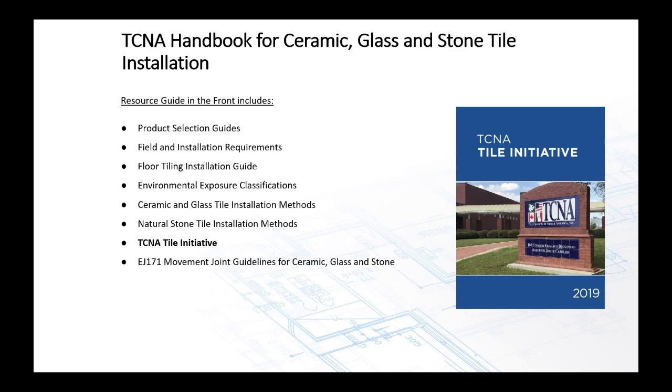Environmental exposure classifications, glass and tile installation methods. These are the actual installation methods themselves, and stone tile installation methods. There's a TCNA tile initiative, and there's some good information there about why tile is green, the Why Tile program, some of the trainings going on through CTEF and the ACT program. So very, very good information there. And of course, the EJ171 movement joint guidelines for ceramic tile, glass, and stone.